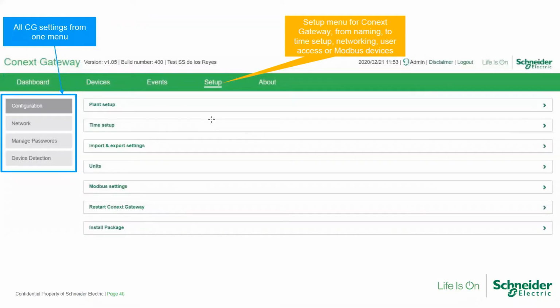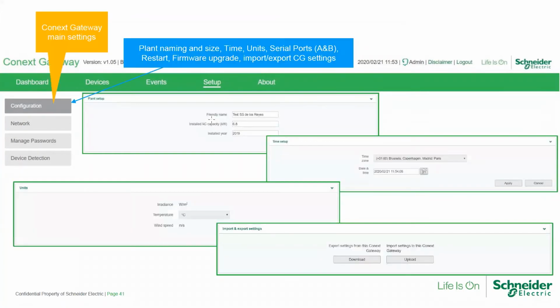So with regards to the setup of the unit, again, the unit has a setup tab where you can actually configure the unit to communicate to the outside world and to communicate with the rest of the devices. Okay, so you see that setup tab there at the top. Basic configuration is date and time zone. That's quite important. Your gateway won't be able to communicate to the cloud if the time setup is incorrect. So that is one to always keep in mind.